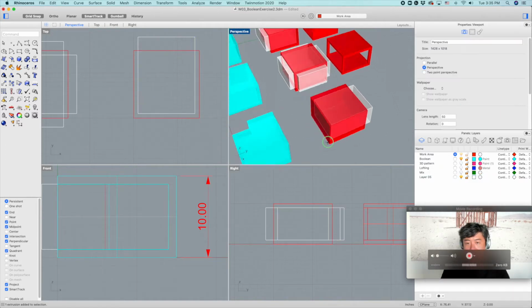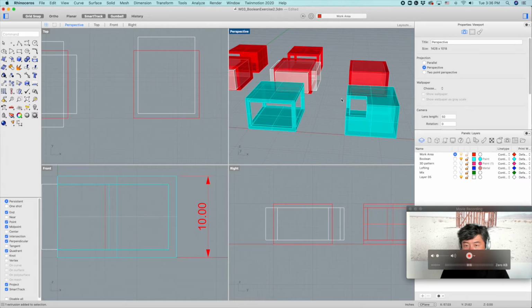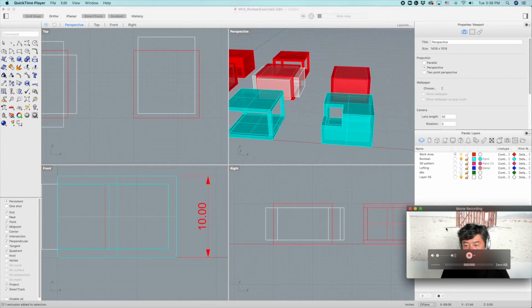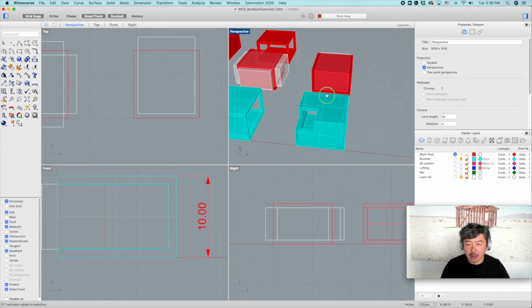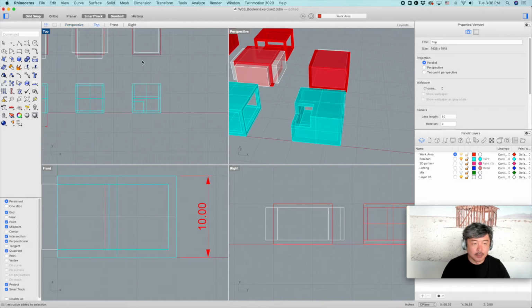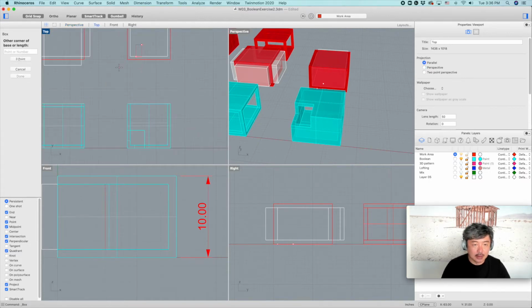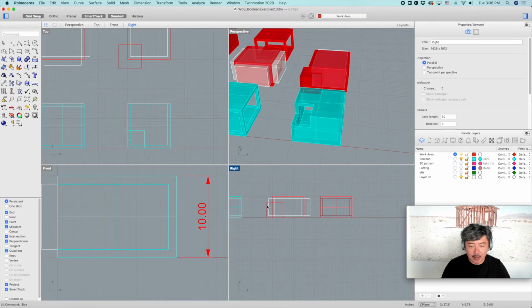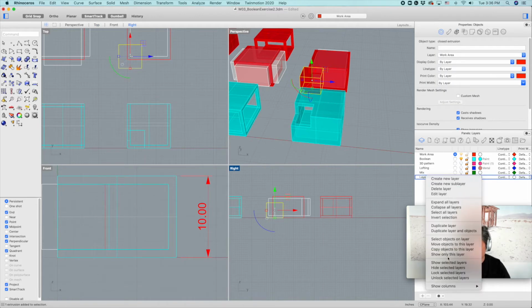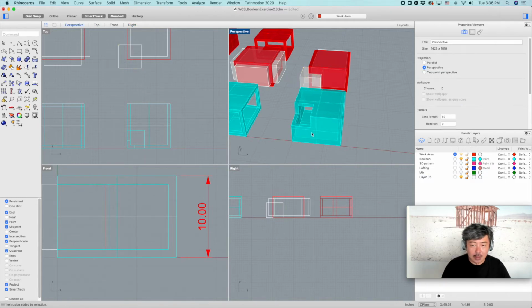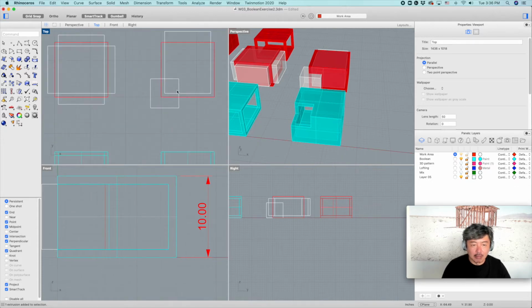So this one also has this hole right here. What we can do is create the hole by creating a box object, make it big, and change it to this layer. Now we can count the numbers on the grid: 1, 2, 3, 4, 5, 6 grids on this side, and 1, 2, 3, 4, 5, 6 grids on this side. So we can match the distance.